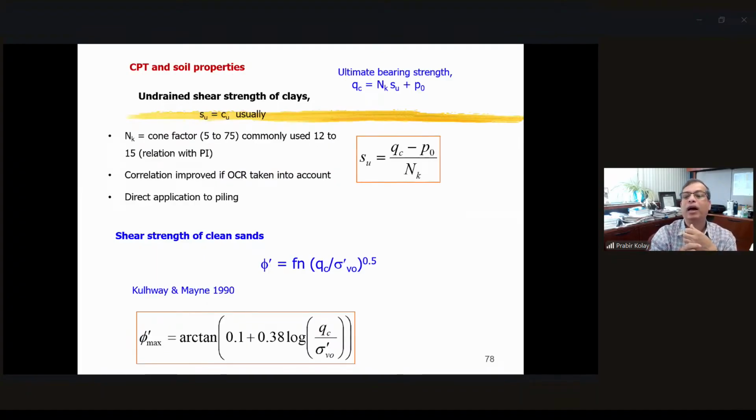And then from the undrained shear strength, there are correlations available, so you can find it out from the CPT. As I mentioned, there are a lot of relations available. Most of the time, either you do CPT or you do SPT test, and the ultimate aim is to find out the shear strength parameters, that is the C and phi values. That's the reason there are several relationships available. So from the CPT value, the cone resistance and the stresses, you can find out the angle of internal friction of the material. And you can find out the undrained shear strength of the clay using this cone resistance.